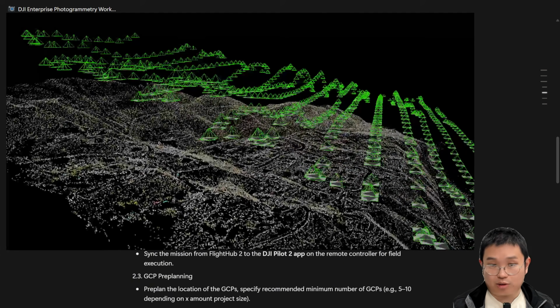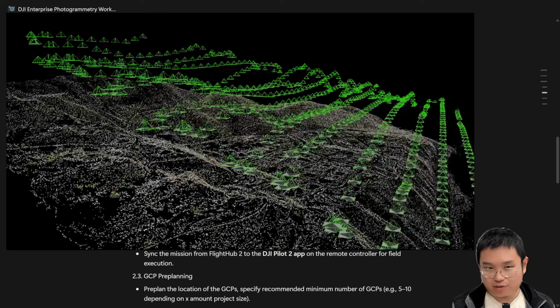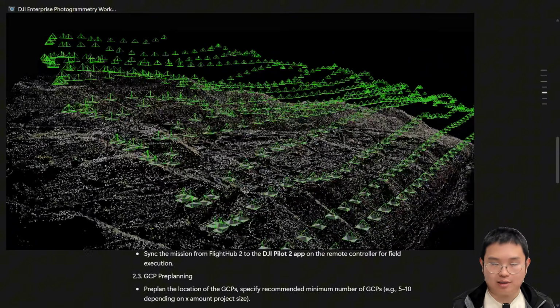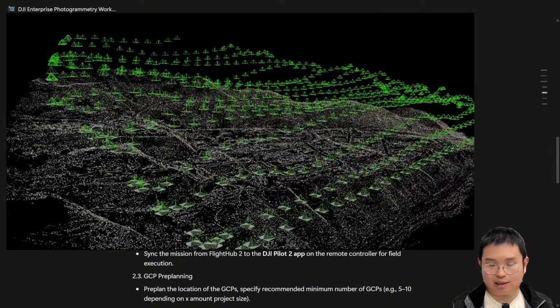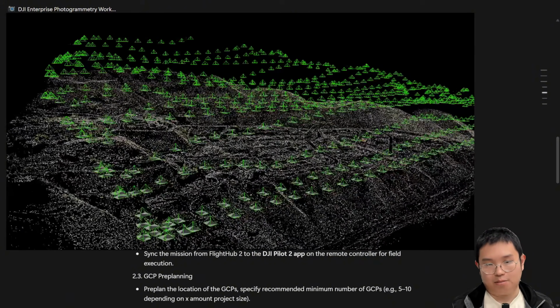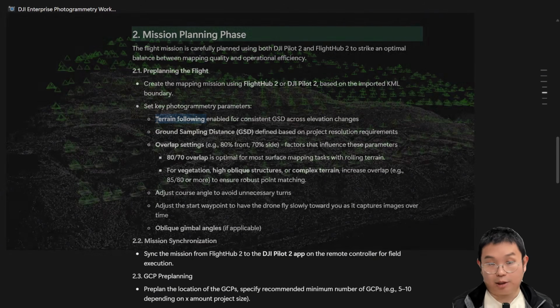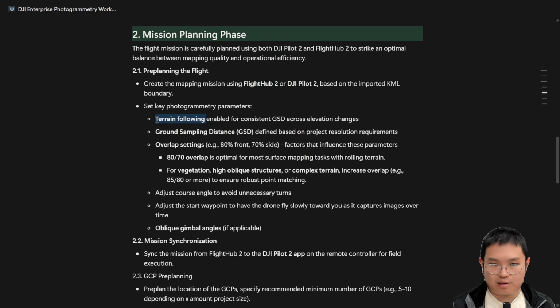These drones support real-time terrain following, using the visual sensor on the bottom of the drone to detect the ground distance in real time and ascend and descend correspondingly based on the real-time terrain. Real-time terrain following is not as accurate as using the digital surface model. However, this reduces the time for gathering the digital surface model or digital elevation model needed for terrain following.